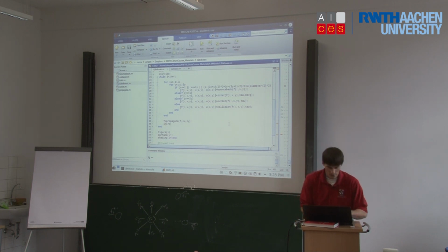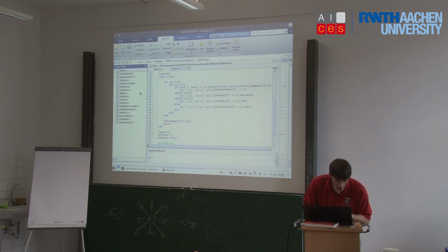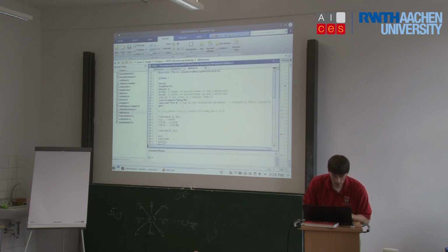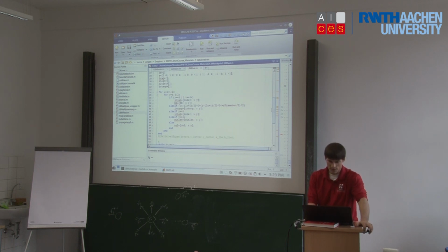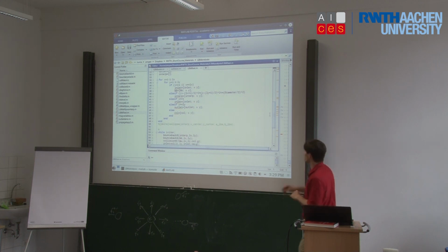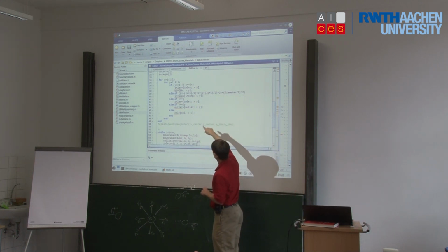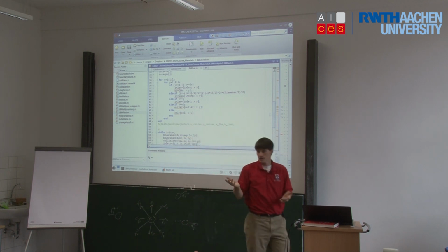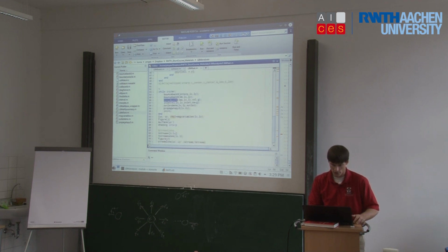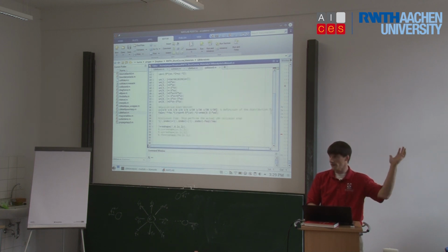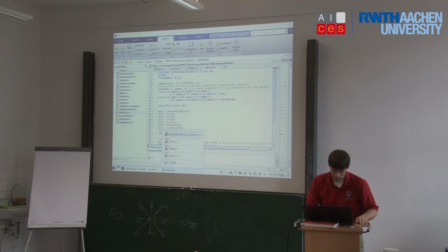And we can look at it right now. So if we go at the analysis option and we look at LBM fast, what I'm doing here, and I'm sure there's, for the computer scientists in the room, much better ways to do this, but what I'm generating ahead of time is a list of all bounce back conditions or all collision coordinates, x and y. And then I'm passing this into this new version of the collision function. And what it's going to do is it will evaluate the collision step for all these points all at the same time. Okay.